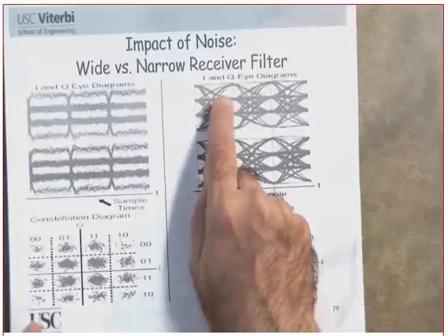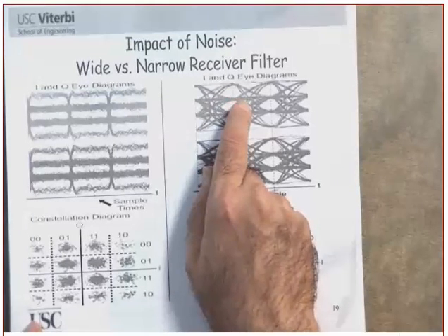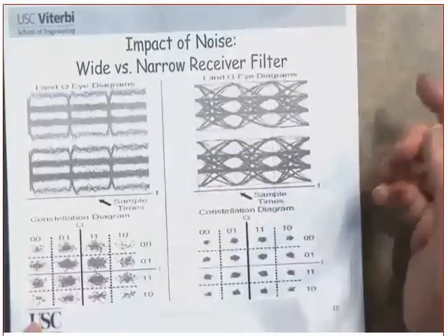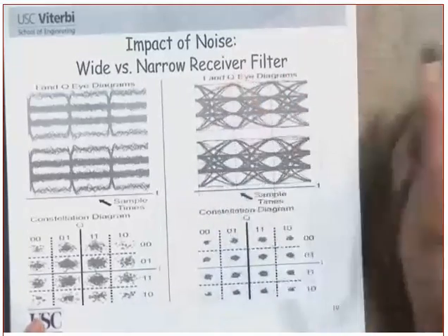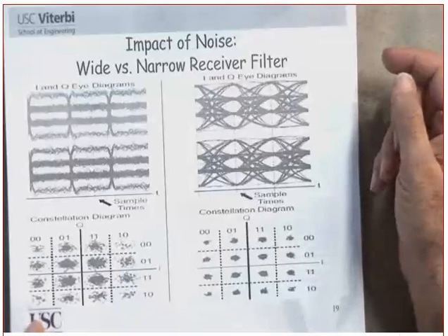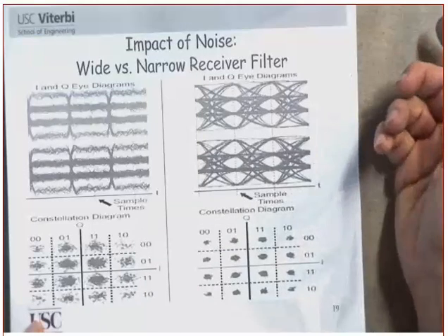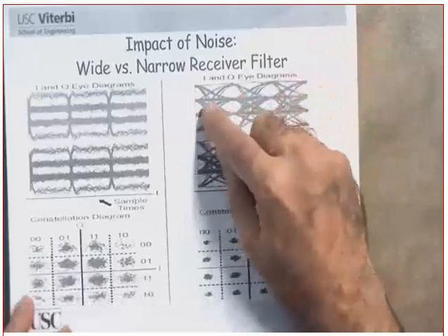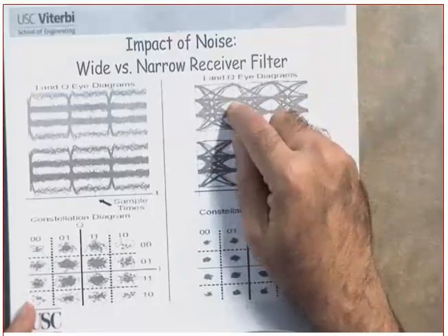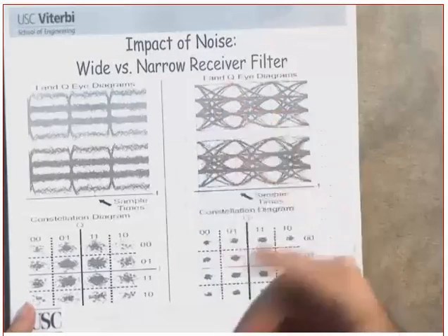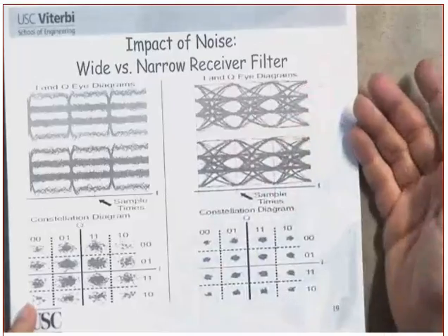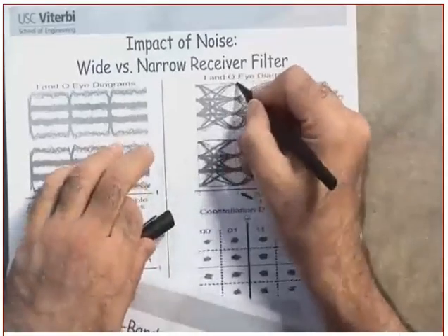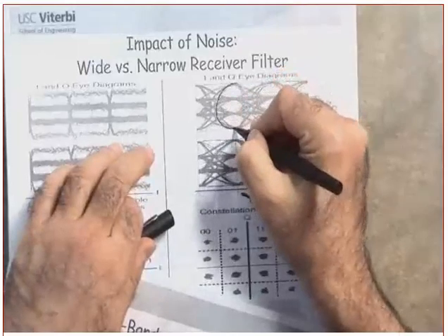All of this distortion, do you see this distortion in the middle? All of this is the result of ISI and the noise. It's supposed to be clean. So I don't understand what you mean by 3 eyes. What, you mean those 3 eyes? Yeah. These, my dear, are the effect of noise and the intersymbol interference. The eye is still closing. This is not the real eye, this one is. Right. That's the real eye.